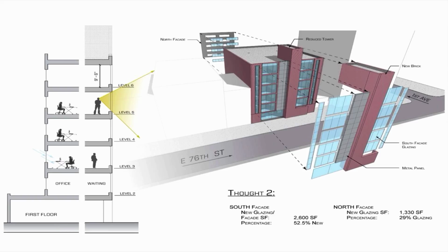So that while I'm studying some design ideas or continuing to work on that, the team's now set up the Revit model and built with Revit components a little bit more accurately that existing building. And because of that shared longitude and latitude, or because we set the project up in FormIt again, the file comes in exactly at the right location back into the FormIt model.